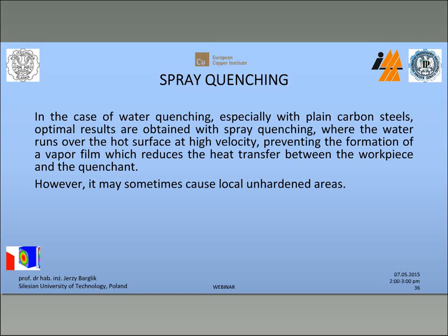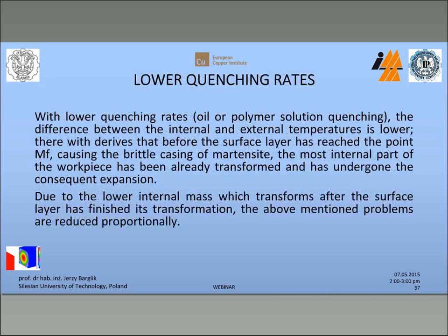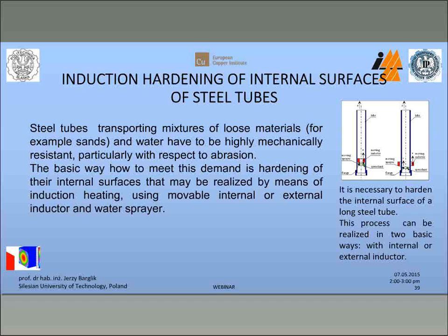A similar problem also arises when we quench by spraying. So there is a reason to use lower quenching rates. Of course it depends on the resulting hardness. So this process should be analyzed during simulation.